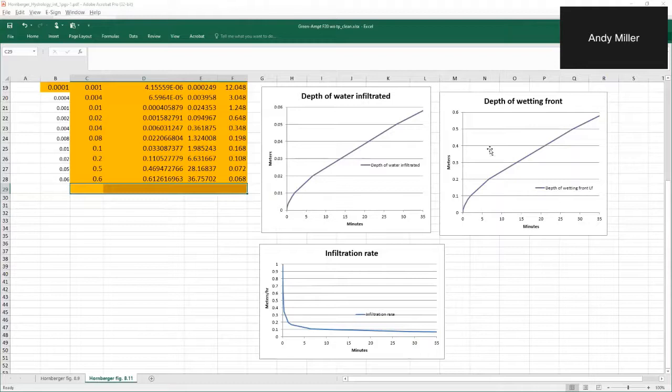In the Digman spreadsheet, explicitly, you're actually comparing the rain rate. And in the Digman spreadsheet, the first thing you do is to calculate the time of ponding, because all your calculations depend on what happens after the time of ponding. Before the time of ponding, the spreadsheet just assumes that if it's a constant rain rate, you've got a constant infiltration rate, which is the rain rate. So the only interesting things happen after you hit the time of ponding, and it's set up a different way.